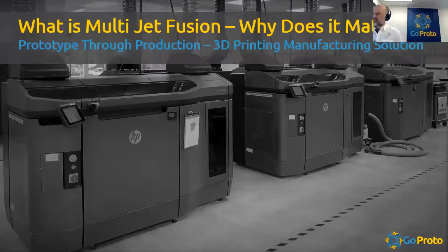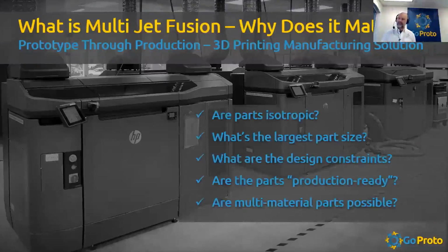I do, yeah. So again, talking about multi-jet fusion or 3D printing and GoProto, multi-jet fusion came on the market in about April, May, June, in that ballpark of 2017. So it's a fairly new powder bed technology. What happens is layers of powder are laid out. Fusing and detailing agents are jetted onto the surface of the powder in the cross-sectional shape of the part, and then a high-intensity energy source is passed over, and wherever the droplets have been applied, the powdered material sinters together, and then that process repeats layer by layer, and you build up your part.